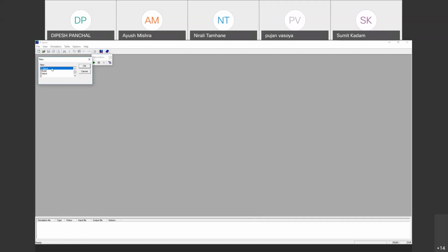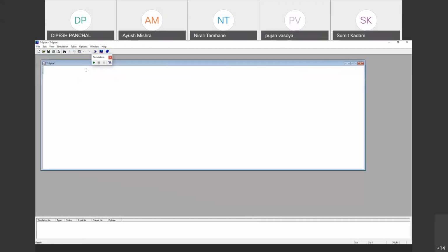Okay, which you want to write. So definitely we are always going to write some code, SPICE code. We are not going to use any ready-made model or write any C language here. So it is a SPICE, T-Spice, you have to pick. So this editor window will appear, where you have to write some SPICE code for the given circuit. I will start with the MOS characteristics. Then we'll switch to the circuit we designed in the theory class, the inverter. I'm not going directly to the inverter.